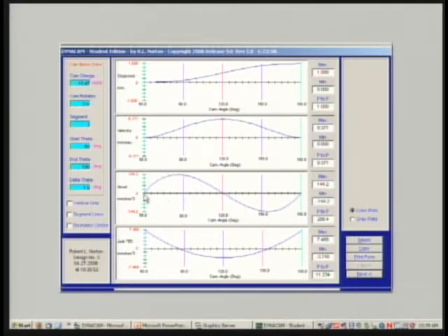This is a 3rd degree polynomial. This is a 5th degree up here. Differentiate, you get a 4th degree. Differentiate again, you get a 3rd degree. So this is a cubic. Differentiate again to get the jerk, and you have a 2nd degree curve, or a parabola in this case. And that does look, in fact, like a parabola. It's discontinuous at the ends, but that is something we accept for various reasons. But we cannot stand the discontinuity in acceleration. So this is an acceptable design.